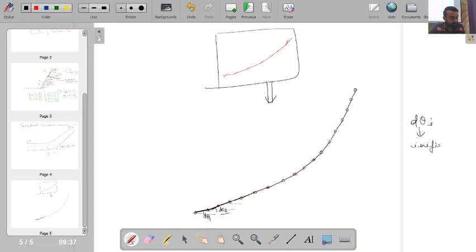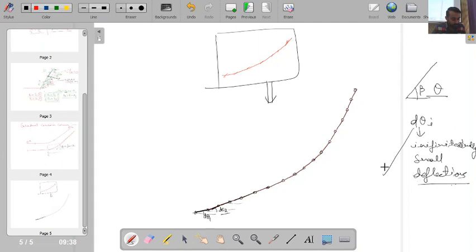and these theta i's are infinitesimally small deflections. Okay, so when I have a finite deflection theta, then I have the presence of a shock wave which has angle beta. If I have an infinitesimally small deflection, then what will I find? I will find a shock wave, but that particular shock wave will be a very weak shock wave, so its strength will be less. If I take this infinitely small deflection, so d theta is infinitely small, it means that my shock wave will also be of infinitesimally small strength. So such a weak shock wave will be nothing but a Mach wave.